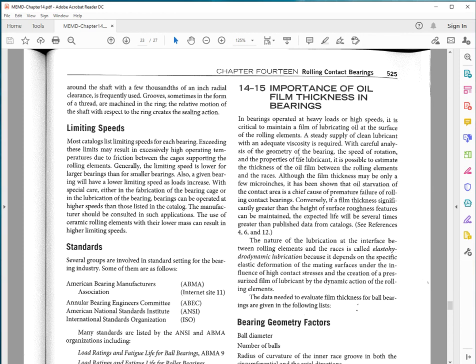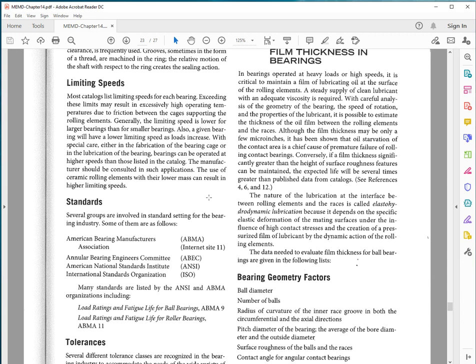Shielded means there is a small gap, and you can periodically lubricate the area behind the shield with solid lubricant, and excess grease drives out the impurities from the interface of the shield with the inner race.